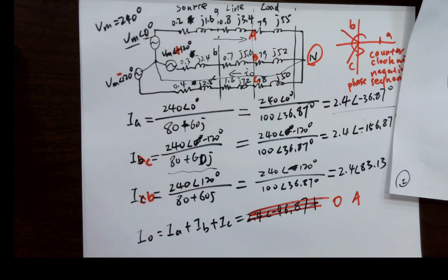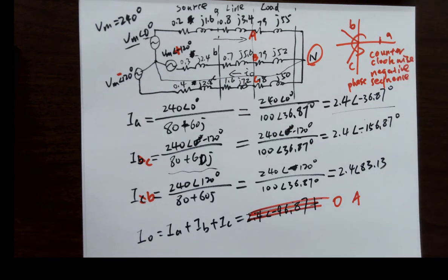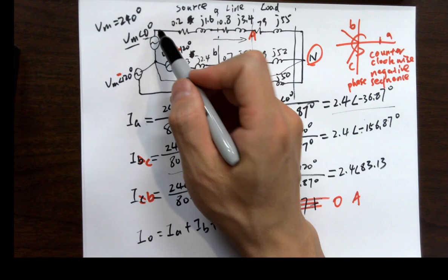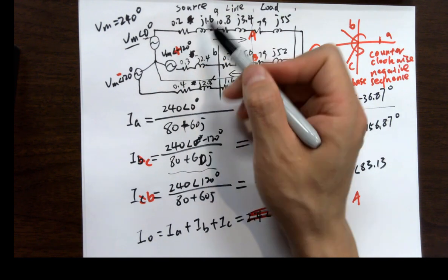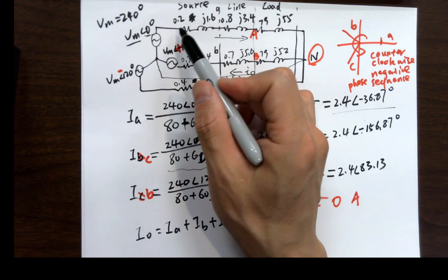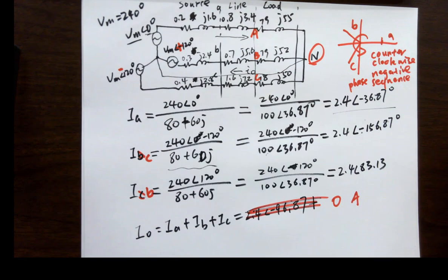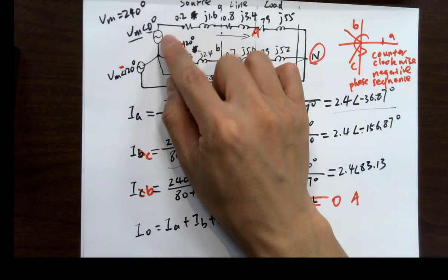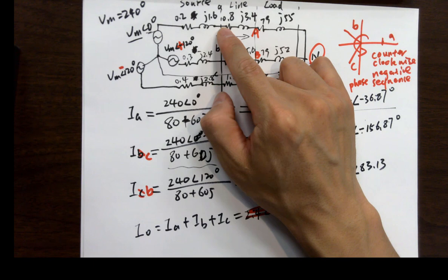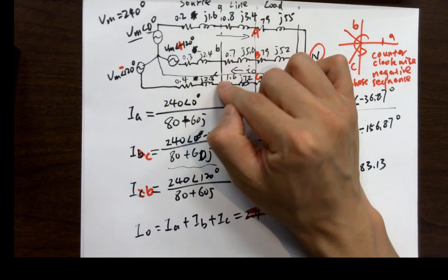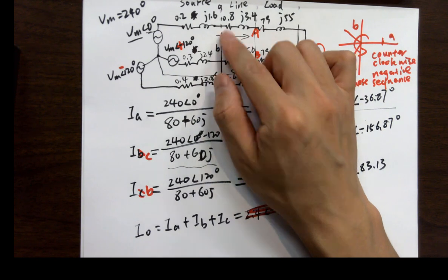However, you just have to know. I didn't know that as well, but it's just asking you if this is a balanced three-phase system. You just have to look at the source terminal instead of the source itself, because the source has an internal impedance. This is the model, right? It doesn't really exist. These are not physical components in the circuits. These are built into the source. So this is actually physically the source terminal. So we're looking at the source terminal here to see if they're balanced.